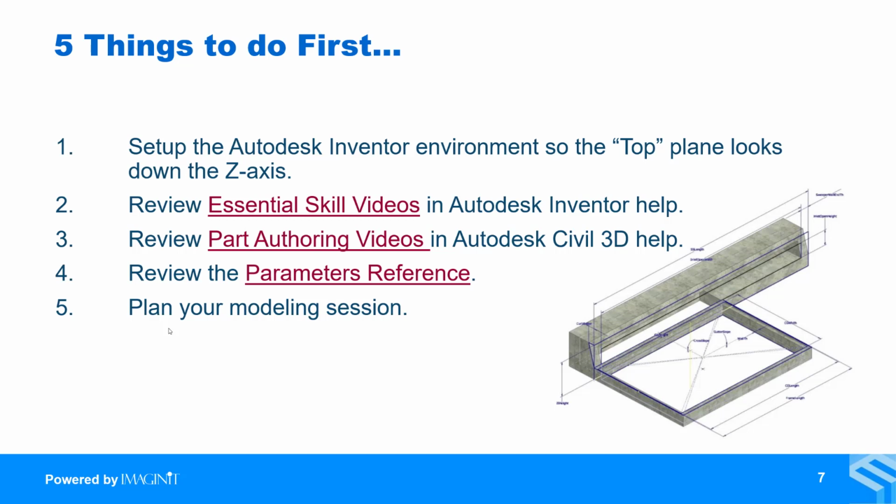The other thing that I would say, think about what application the part is going to be inserted into. Nine times out of 10, that answer usually is Civil 3D. And keep in mind that Civil 3D does a great job of showing the structure in plan view, profile view, cross-section view, but we don't need to model it to the nth degree because we'll never see some of that detail inside of Civil 3D.